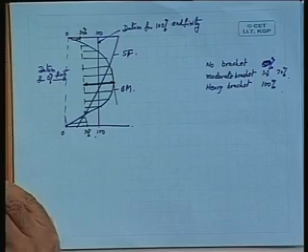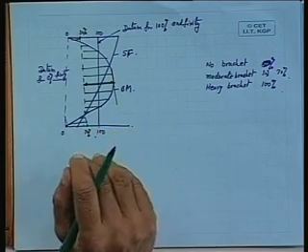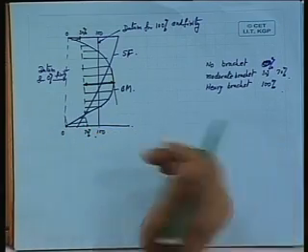So this 30% and 70% fixity is one small difference. See, depending on the bracket, suppose I take a very small bracket on the top, obviously it is not 0% fixity, because if there is no bracket, then it is 0%. So, if I give a small bracket on the top, from my experience, I have to say whether it is going to provide me 30% fixity or not.